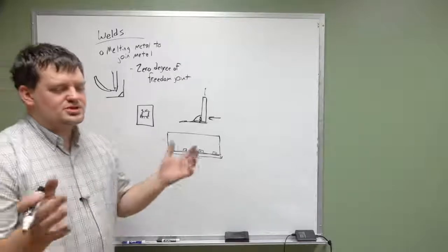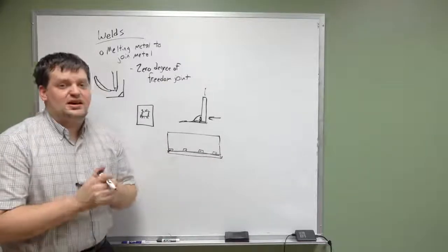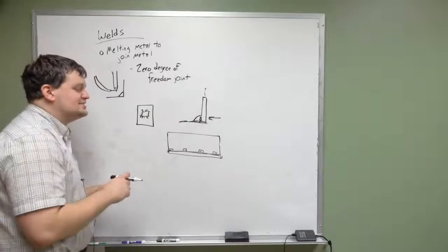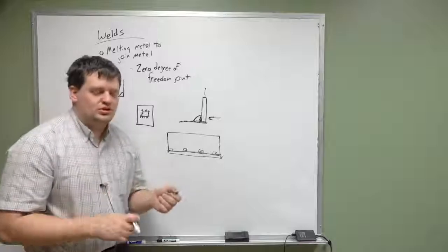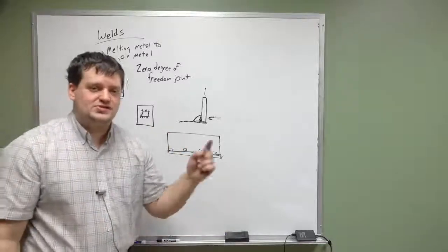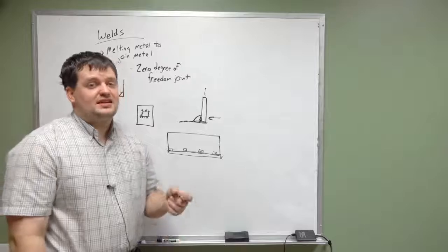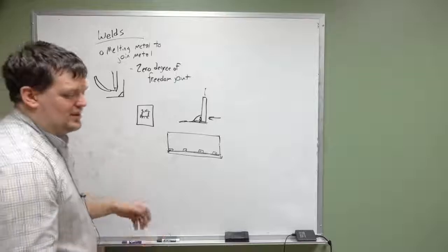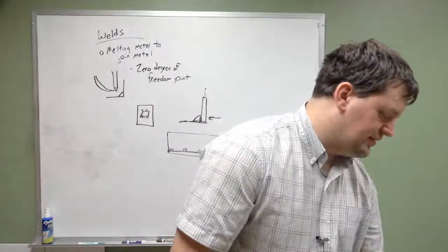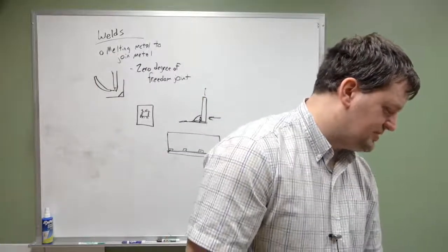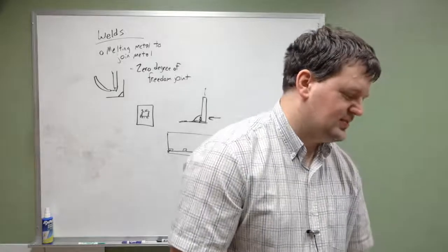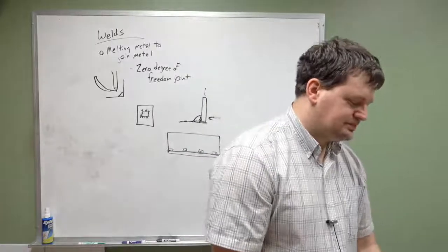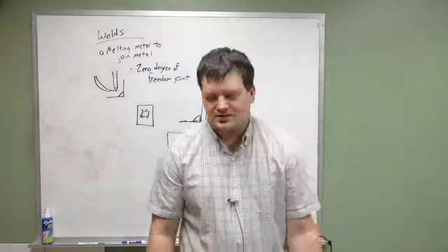Okay. So determining the forces that it can handle, that's great. Now, as the designer, what you need to recognize is that there is some fatigue involved too. That is for a static force that is applied. In order to do your fatigue, you have to modify all of this. Oftentimes it's just a value that you multiply by.